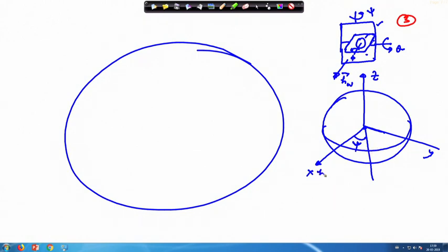Okay. So, suppose the h vector, h wheel, is directed along this line. It will come to this position once you have rotated from this position to this, and thereafter I can rotate it from this position and bring it onto the surface of the sphere anywhere. It can go, and this angle, let us say, is theta here in this case. So, the h vector comes here in this place. So, by rotating by psi and theta, I can point this h vector on the surface of a sphere at any place. Okay. You can go to any place.